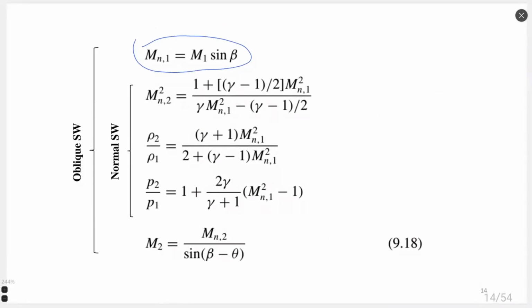If we write this in terms of our thermodynamic properties, because we already had a model for the oblique shock wave, this first step, step 1, when we split our system, is written here in a very simple way. We just need to know the angle of the shock wave, and we can perform such a calculation because the Mach number is a value which is given before calculation. We know it's our initial value for calculation.